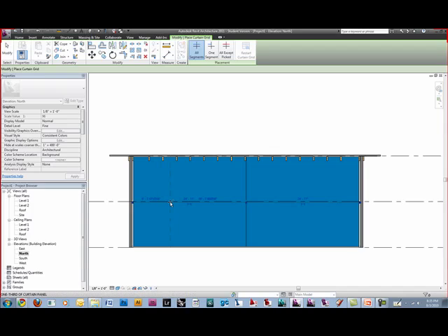It's going to move in even distances of 1 foot at this zoom level, and then all of a sudden it'll break it up like 8, 3, and 17 out of 256, or 171 out of 256, and all of a sudden it'll snap. That's telling you you're in thirds. So I'm just going to go to one segment and start adding in some grids here at midpoints. Once you've placed a curtain grid, you can also go back and edit that.